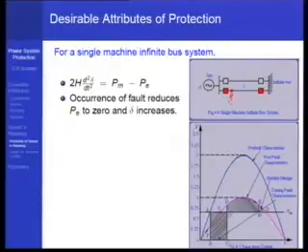But even though the acceleration starts, the speed is still much below the synchronous speed, and therefore the rotor continues to retard in delta until you hit this limiting point somewhere here, where the speed becomes equal to the synchronous speed, and now still accelerating power is available.